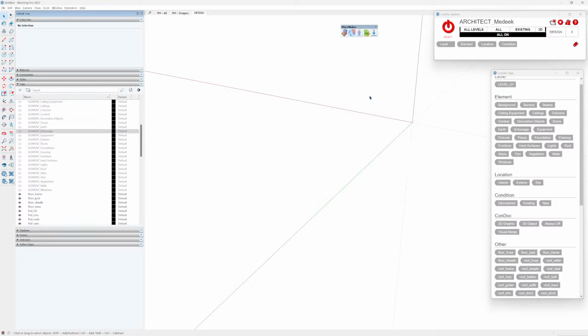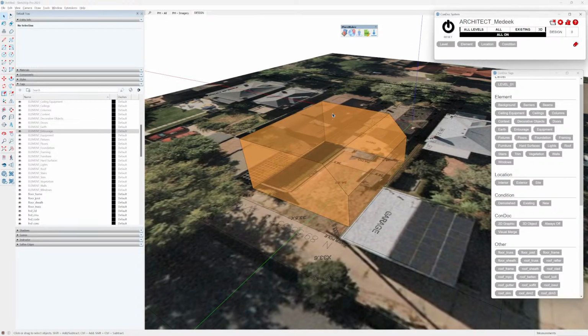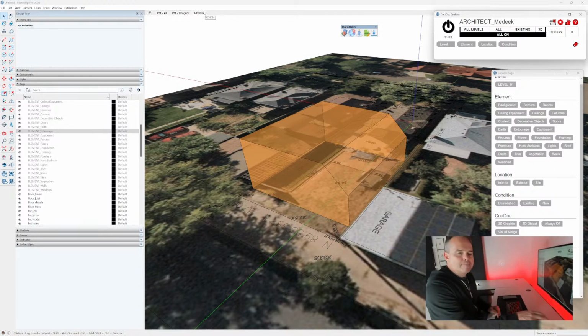If I hit the reset button, that turns my tags back on. Essentially, when I hit that reset button, it pings my design scene tab. When I ping that design scene tab, any properties that are set up to save on that design scene tab are triggered. So that makes this reset button really pretty slick to customize.